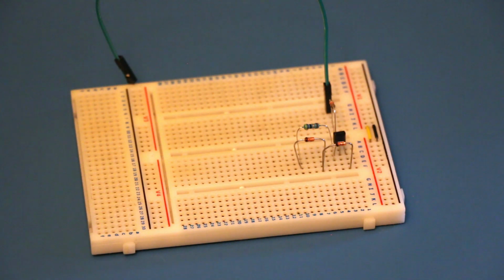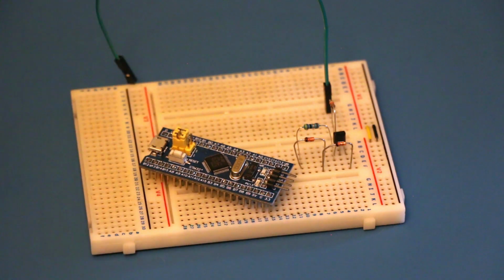The dev board we're going to drive the chain is one of these generic blue pill boards. It has an STM32F103 on board, and though there aren't any specific peripherals which will work directly with the chain, we might in the long run be able to coerce some timers and some DMA operations to make it work nicely. It also has a USB interface, which means that we could potentially control the chain from a computer, which is one of the long-term goals.